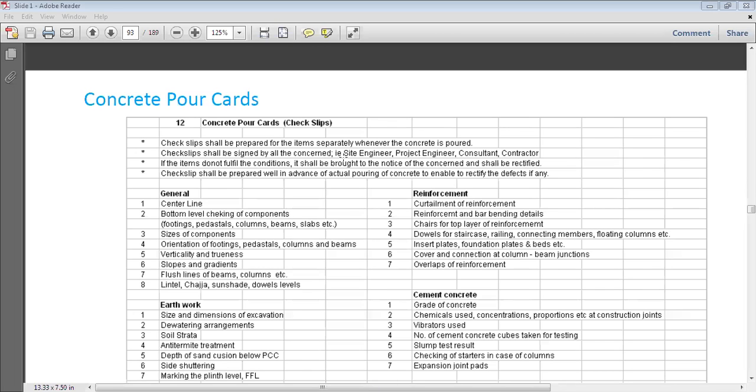Nowadays the rainy season is going on, so there is a lot of water which is going to be saturated in the excavated area. So you need to dewater that particular area completely. It should not be that water stays saturated for 3 or 4 days and the soil nature gets changed. Definitely the ground water level in that soil will increase, and that will hamper your construction.